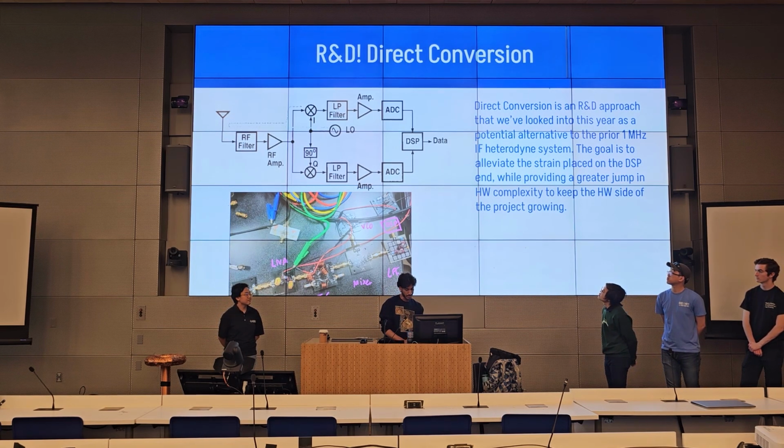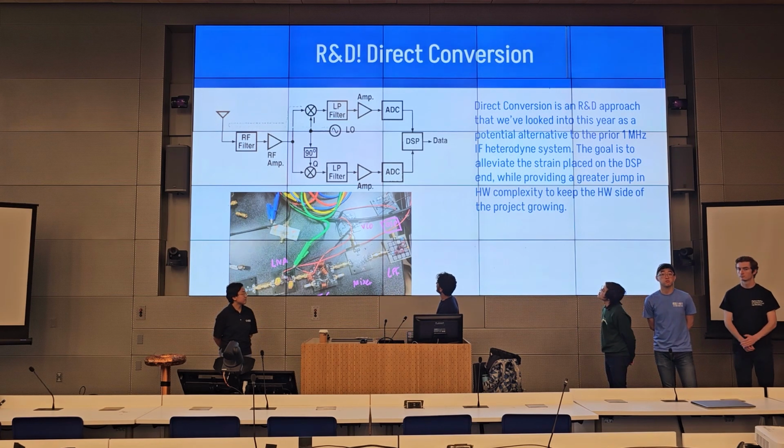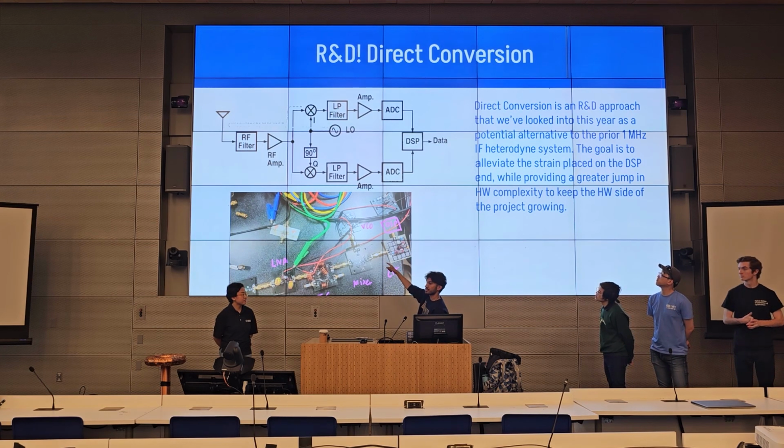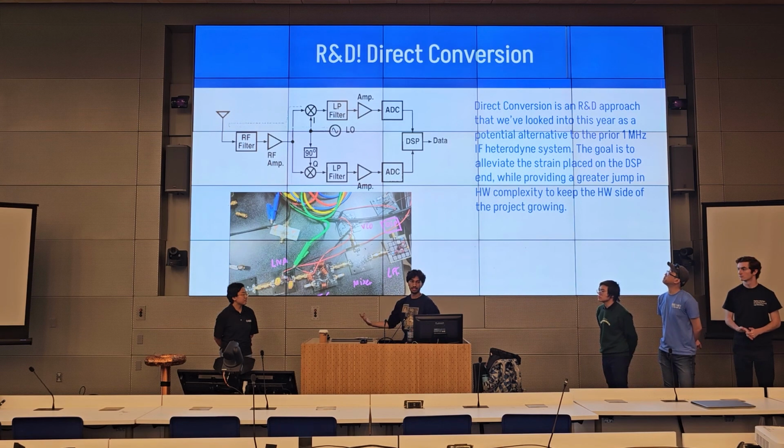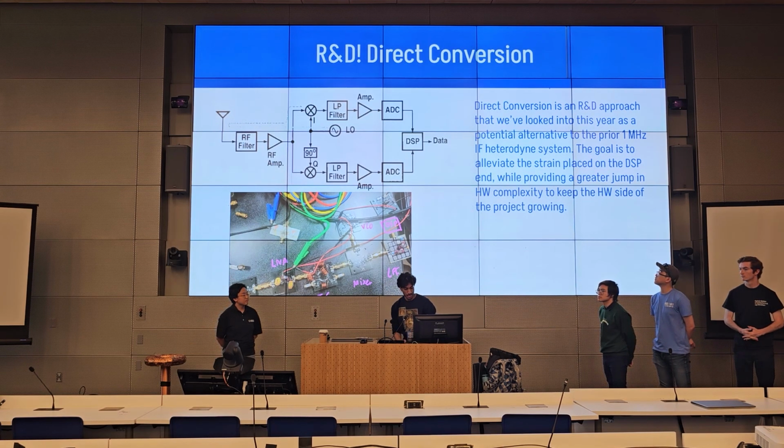You can see that there's an LNA, and the bottom of it got cut off, but that's an IQ generator here. And next we go into the mixer we've seen before, a low-pass filter, and our DSP block, and we have a voltage controlled oscillator as opposed to just a normal Colpitts free-running oscillator. So it's hopefully a more efficient method of doing the same thing that we have outside.